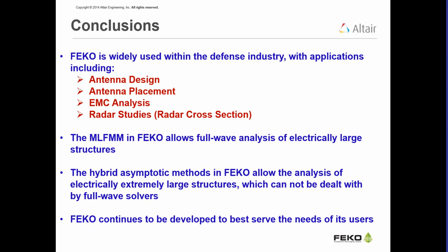I have the second question here. When using the NGF, the numerical Green's function for rotor modulation, do you need to create separate files for each rotation angle of the blades? No, actually you can do Lua scripting in FEKO where you can create one file and then go through the scripting to say keep running this program and also changing the rotor blade angles and use the NGF file that's available. So you can do this all in one project.